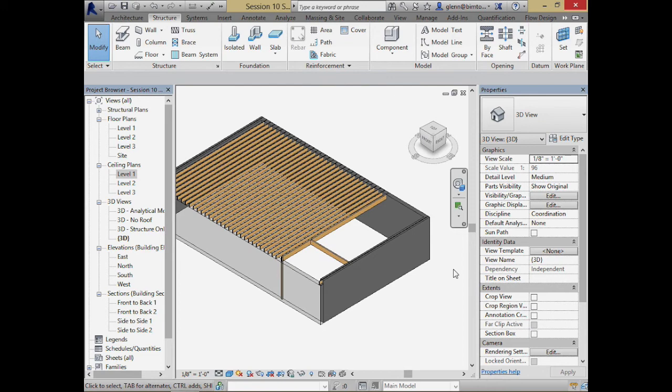Okay. Well, think about that. We should do some looking up about Adobe in this area in terms of whether we need another structural frame inside. With Adobe, we can get some sort of hybrid, whether it's pure earth or whether we put some concrete in there and then cover it with Adobe, because one of the rough things is that Adobe typically is not very good for lateral resistance.